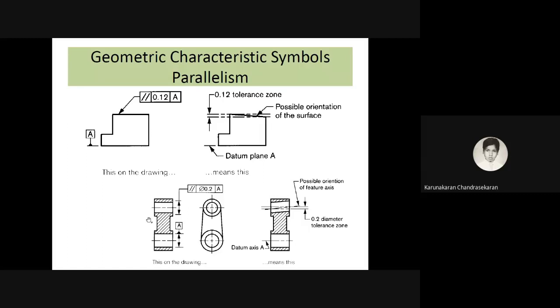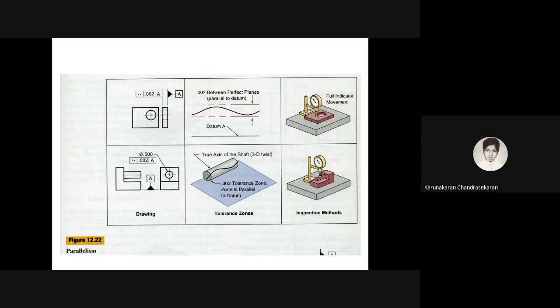Similarly, when you have this particular two holes reference, you just observe from this reference how much deviation you are going to have, because this is nothing but an axis you are giving. Even for an axis, what is the allowance you are going to give? That has been mentioned in this. And how do you measure parallelism? Just use the same dial gauge, use full movements, take the values and represent them with the parallel modifier, and you have deviations of 0.02 with reference K.